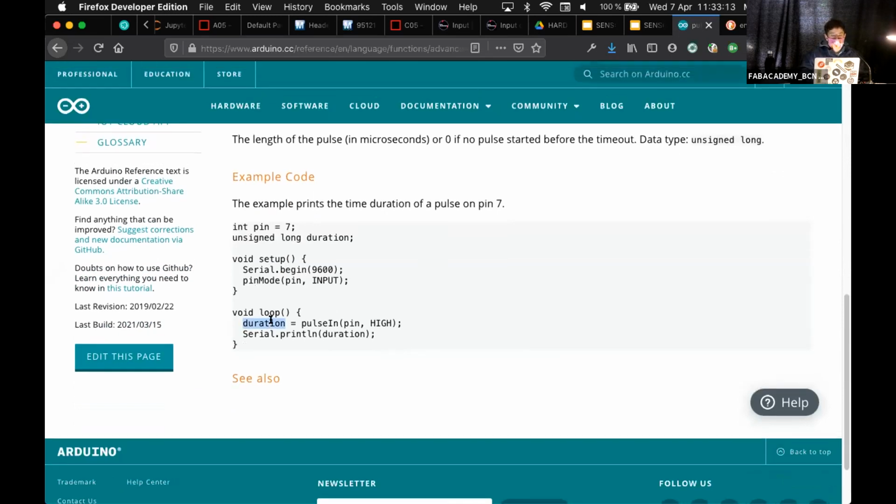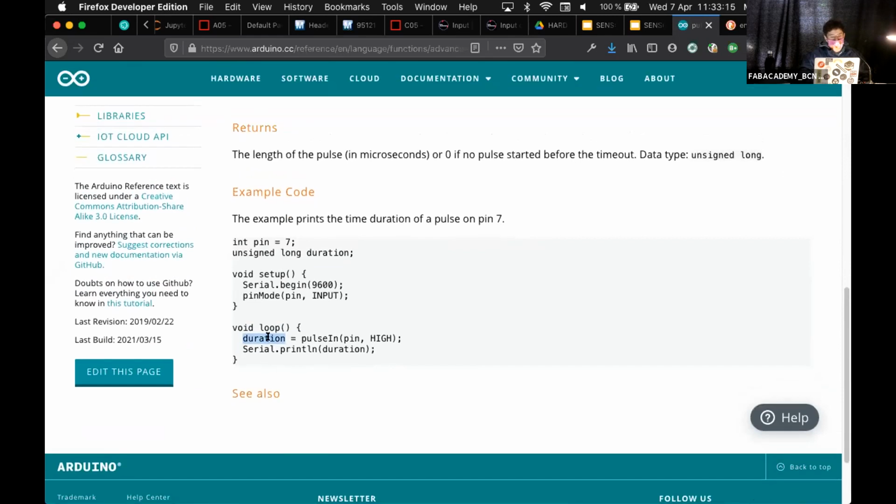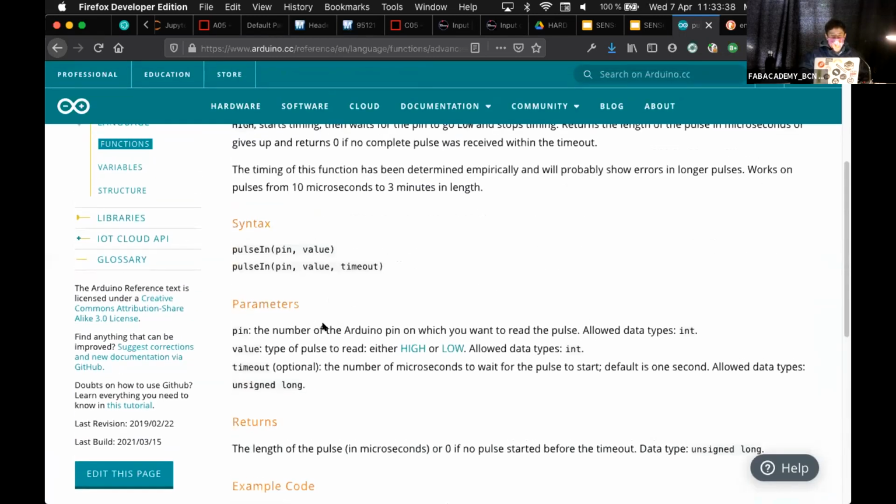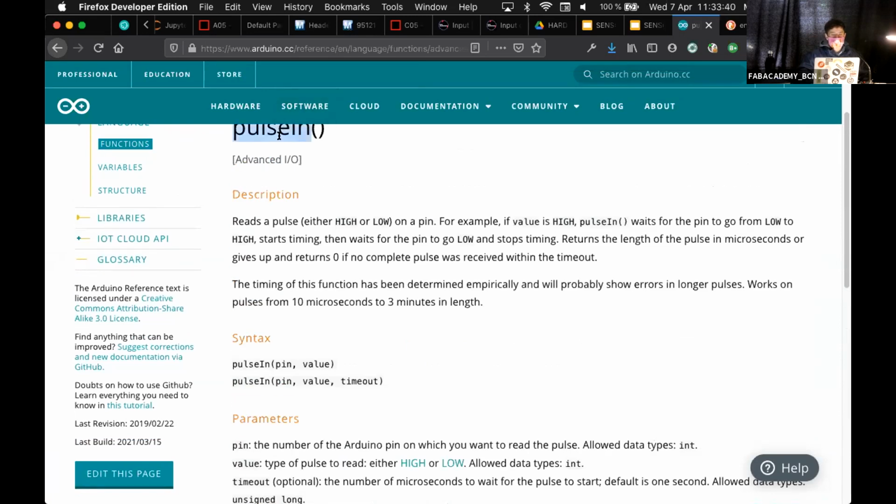Then you can just convert this number into, I don't know, per every rotation I have a period of time of, say, 30 up and 20 down. I convert that duration and I'm able to estimate, for instance, wheel speed or rotational speed of a motor, etc. Simple function that might help many times.